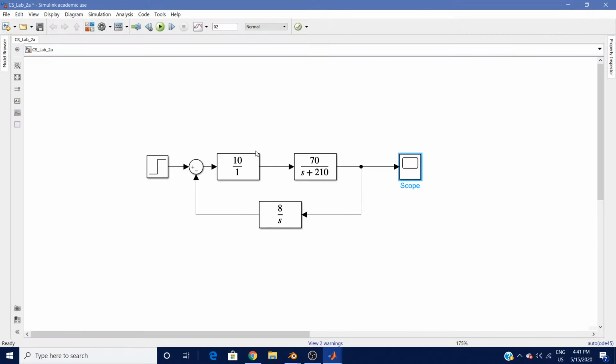But the basic system, this is just so that you know that this is called the forward path, which is going straight in, and there's something called feedback, which is the output multiplied by some value. In this case, it's being integrated and multiplied by 8, and it's being given back and subtracted from the next input, and that subtraction says that this is a negative feedback. We could also have positive feedback and so many other things, but we'll not get too much into that. Hopefully this gives you a general idea that most systems will have a forward path and some form of feedback. Some systems do not have feedback, and those are called open loop systems.